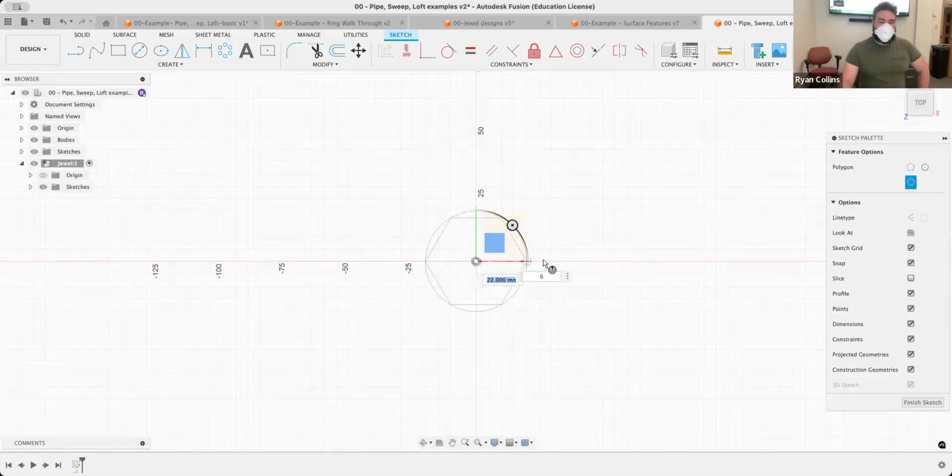Okay. Now you see as I mouse out, I have a couple of tabs that come up. I have my dimension, my radius for the circle. If I want to make it giant, sure. If you want to make anything smaller, great. And then I have the sides. Do not hit enter. What you need to do in order to change the amount of sides, press tab and change over. I'd recommend increments of 6, 12, basically anything higher. Even numbers though. Make sure it's an even number.